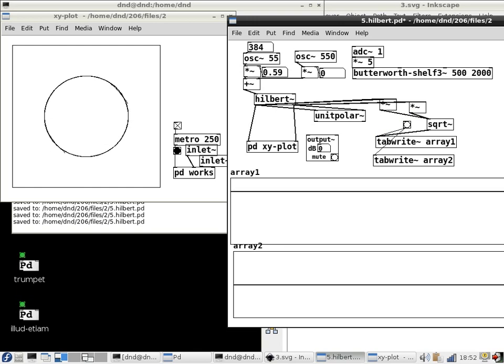So now, no matter what I do here, I've got a signal which is equal to the amplitude that I'm putting into the oscillator. Sort of. I suspect if I go changing that at audio rates, there would be some lag in the measurement of the amplitude for various reasons that I would have to explain in terms of modulation. Like if I sinusoidally modulated the amplitude, really that would be adding other components, and then I would have to talk about beating effects. But nonetheless, if I put a nice clean sinusoid in, I get a nice clean amplitude signal out.